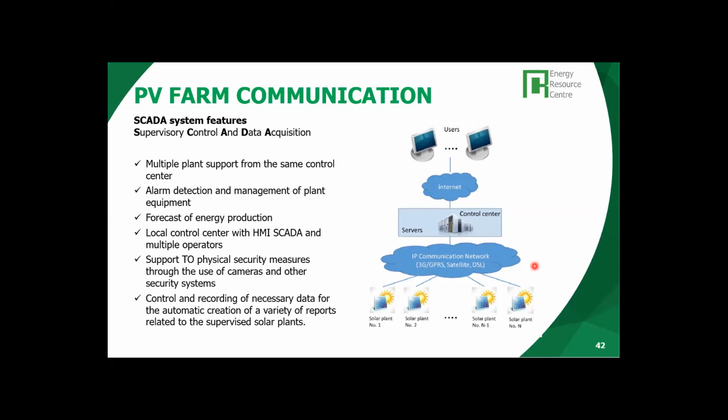So this communication element in PV farms is critical, and this has to be necessarily well defined in the projects that we want to build. Sometimes the temptation could be to first proceed with the construction of the PV farm and then come and retrofit, install the communication system on top of that.